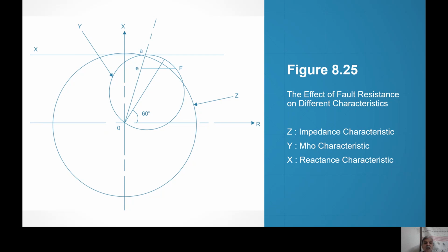So the fault resistance is highly comparable to the line resistance up to the fault. Therefore, in such cases where the lines are short, reactance is better.